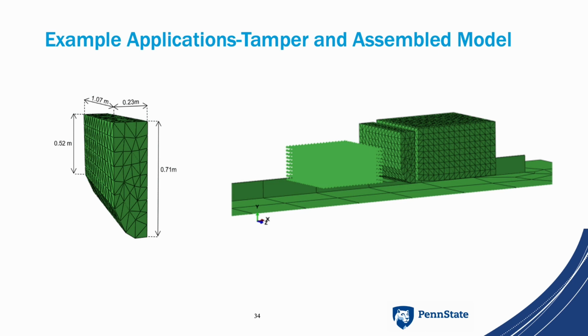As a result of the impact of the paver vibration, the unit line pressure is greatly improved. And when the vibration paver continues to make rapid impact on the surface, the same frequency of the pressure waves penetrates into the material layer, causing the material particles to move.